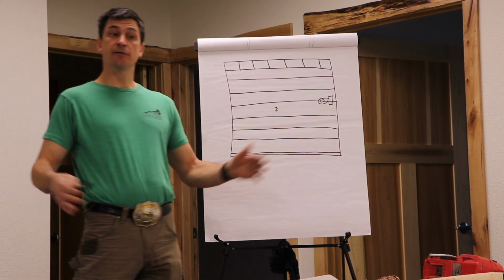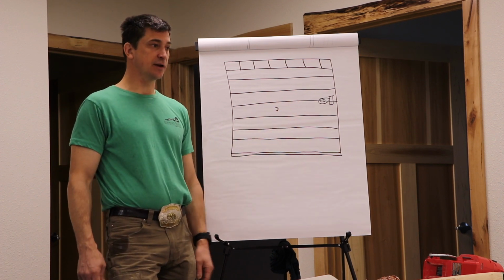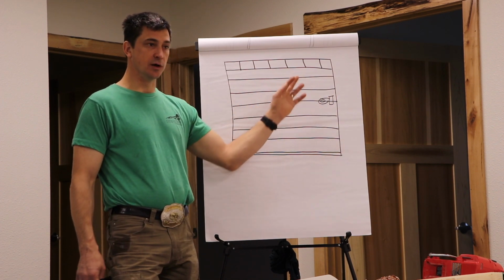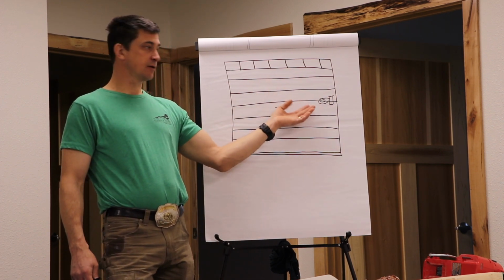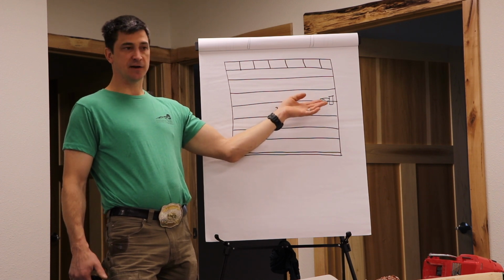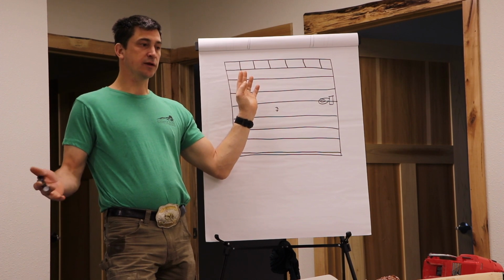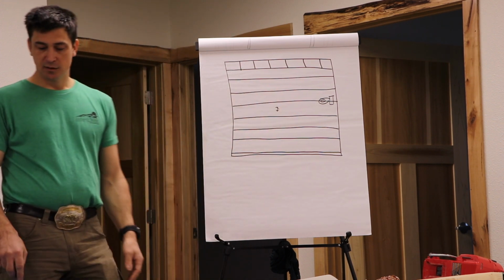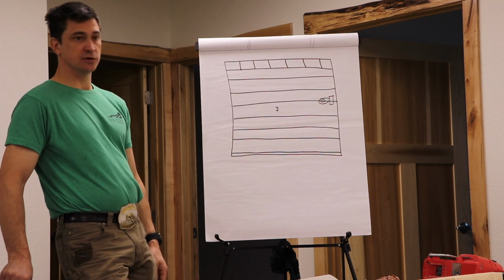So generally, at that stage, it is way too late to change a bathroom layout. So they hack the floor joists off, you run a new one, and it's a ton of work. Where if you paid attention to that right away, it takes like 45 seconds to move your layout a little bit, and maybe 20 minutes because you got to cut your sheeting off a little bit different or something. But way less work than having to put a new floor joist in after the house is completely framed.